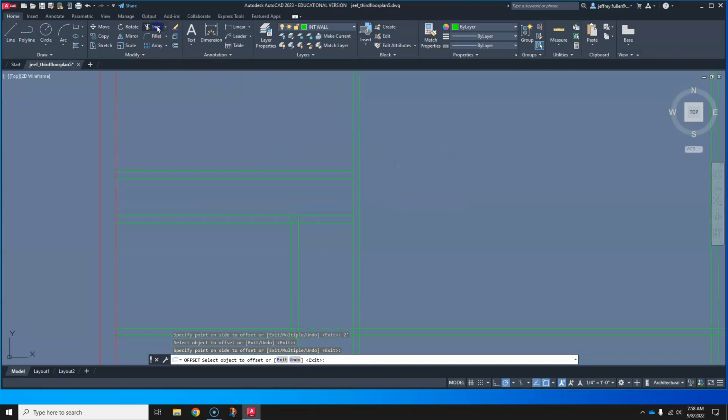I'm going to go to the trim tool, click on that, hold the shift button down to go into the extend mode, and just draw across those 2 lines to get them to extend to that wall. Then I could trim those. Well, actually, let's do this. Extend that one a little bit more. Now I could trim just like that. Okay, so now I've created closet space for this room.